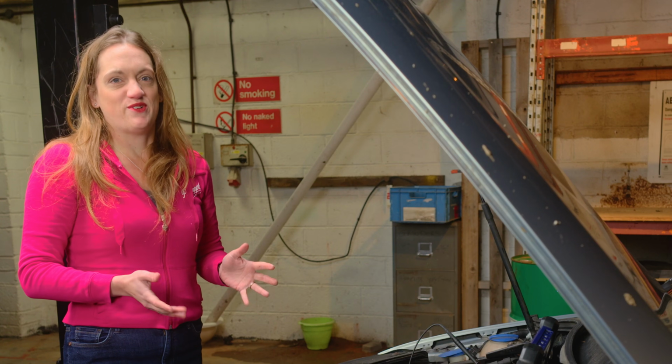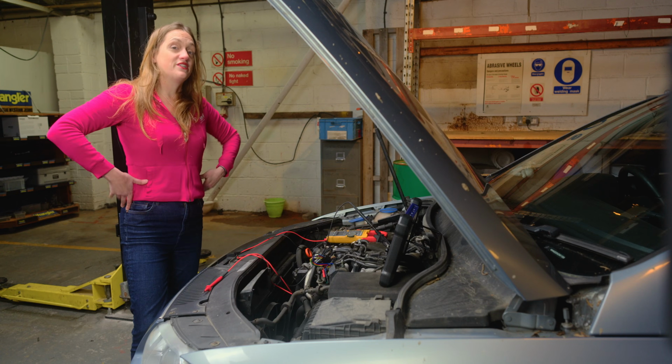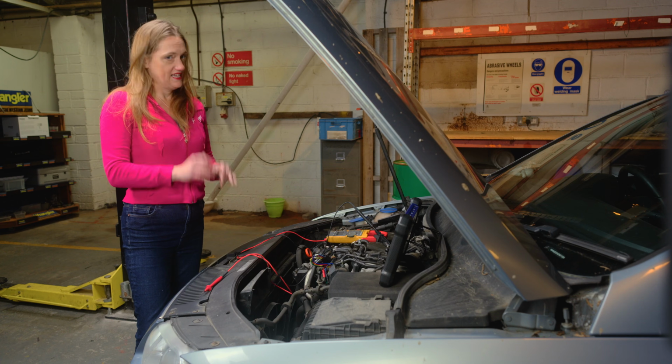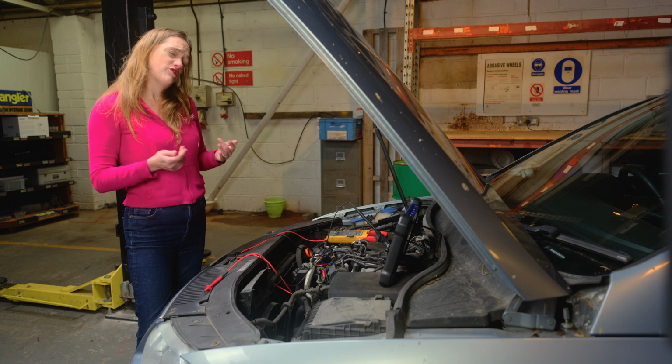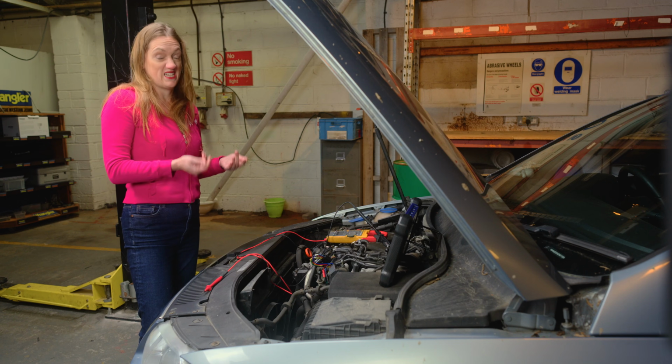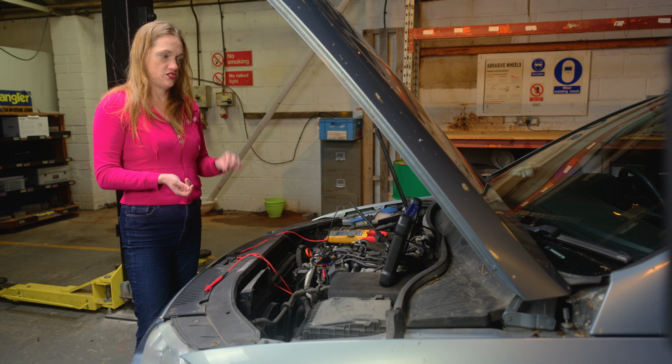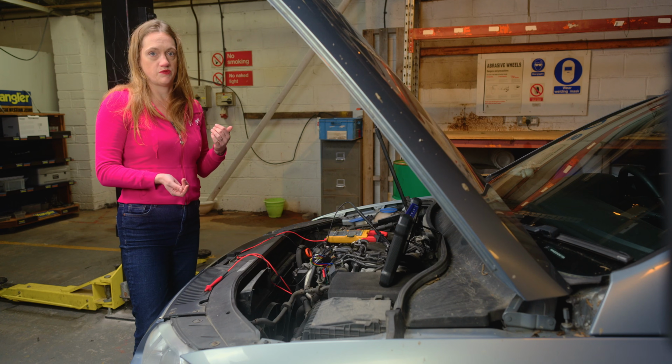Well, that wasn't really that helpful actually, it hasn't told me anything. But what I do know is the motor is not moving. I'm of the opinion that I haven't got a problem with the wiring, and with the fault code being what it is, that we've actually got stuck flaps. So it is just a case of whether or not the motor's burnt out as well.